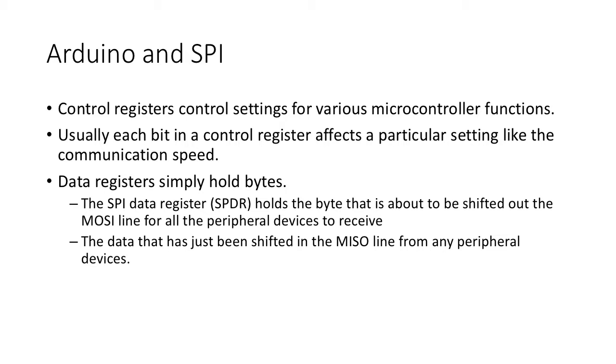What you do is you insert delays in order to do the transfer, and there is no intrinsic acknowledgement. In other words, you can push data out of the master out slave in and expect that the data is being transferred, but unless you're listening for an acknowledgement from the slave, you can never know if you aren't just dumping data out into the ether.